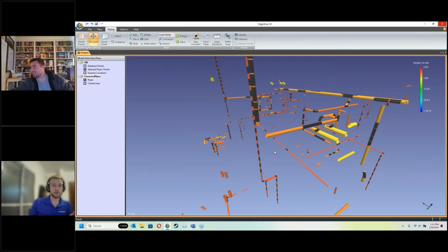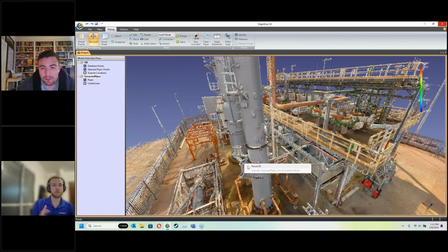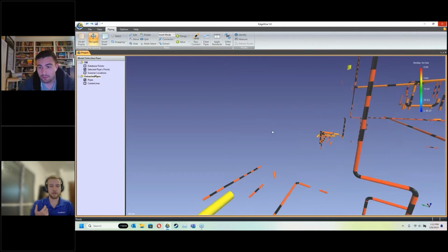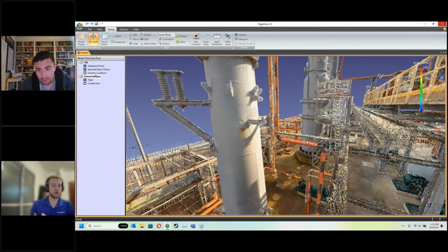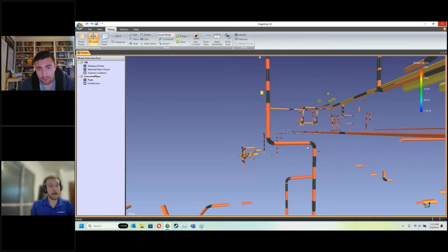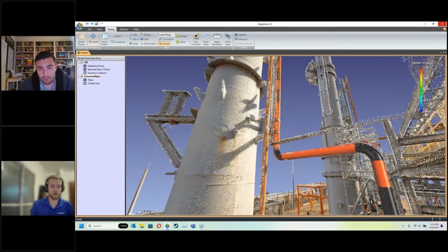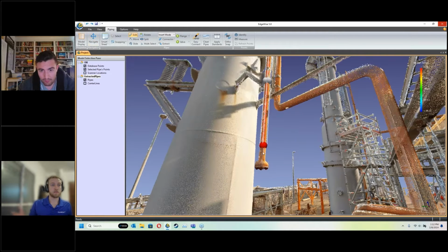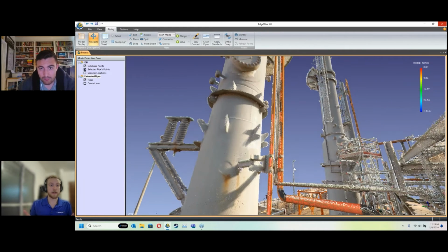And it's computing on your computer, right? So the better your computer, the faster it goes. Yeah, 45 minutes to an hour of scanning, some processing time on the NavVis side, and then about 45 minutes of processing on the data from the EdgeWise side. But we're looking for cylinders, and then we will find cylinders in space, fitted to the point cloud, and then with this Easy Connect tool, it'll go through and very quickly fill in the gaps between connections, including elbows. So we'll see a bunch of that. Long complicated runs can be done pretty much completely automatically, essentially.